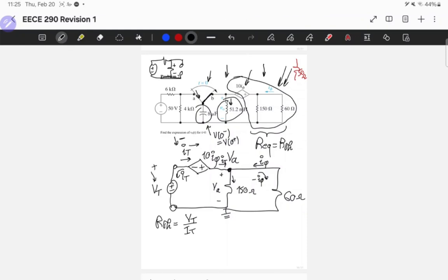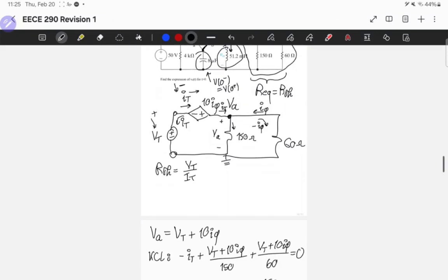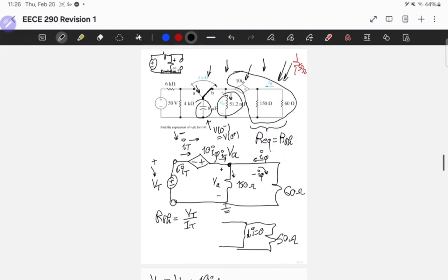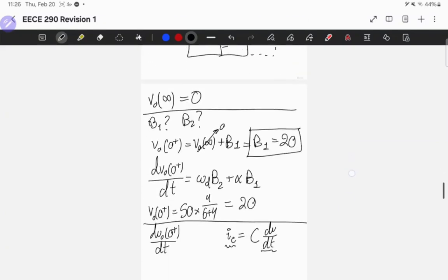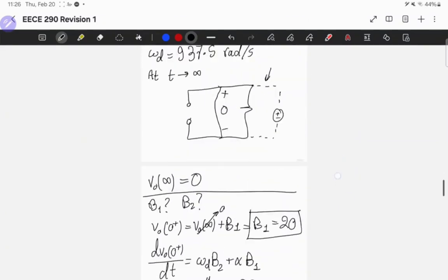So I need the current in the inductor, but we noticed that before switching, this was disconnected from the capacitor. So we had the inductor being a short circuit, steady state, and effectively this 50 ohm resistor. There is nothing in here, I equals 0. There's nothing feeding current to my circuit because we have this switch at B disconnected. There is nothing in here. So IL at 0 minus is 0, and oops, sorry.